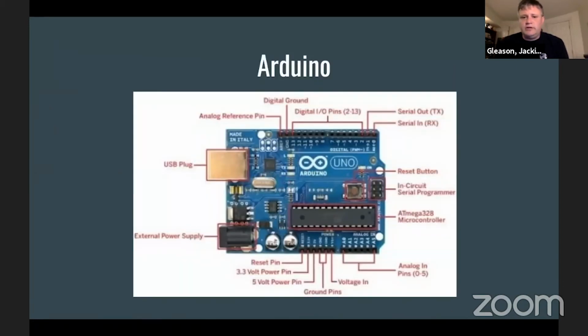Okay, so the next thing we want to talk about is Arduino. When we're talking about Raspberry Pi, one of its limitations is that it's digital only. So sometimes there are things that are better done through an analog signal, and one of the nice parts is that the Arduino boards support analog signals. The other nice thing is that they support serial interfaces like USB, which we can use to communicate back to our parent board, if you will, our Raspberry Pi. So that's a really important use for the Arduino boards. Even if you're using the Raspberry Pi, sometimes you'll want these for the analog pins. And like I said, it plugs right in, no problem. You don't need a power supply or anything, because the USB self-powers it, and you can plug it back into the Raspberry Pi.